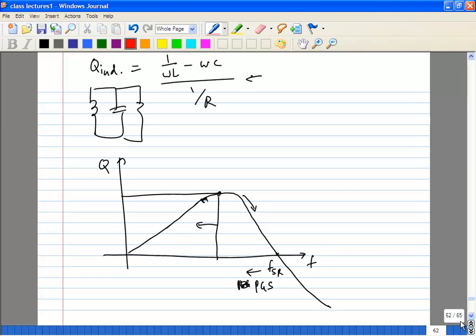You will find a few cases where you would end up matching to 50 ohms, in case of impedance matching, right? But there we are already assuming lumped element matching. You are already assuming you are using lumped elements to interface with distributed elements. You know, a lumped L and a lumped C of certain values will transform the impedances from 50 ohms to 200 ohms, right? So there is no problem in using lumped element models.